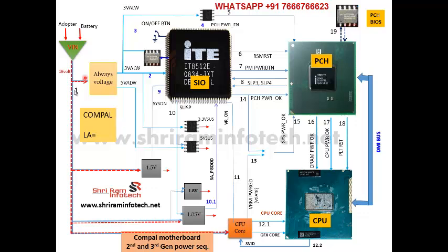So now when I connect the adapter, all these sections work only after they get enabled. Only this section works directly. So once he receives the input voltage, he generates this 3.3 and 5 volt. See how the voltage is going.